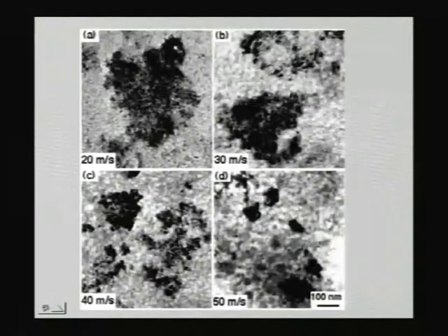And if you use different cooling rates, one can get different grain sizes. As you increase the cooling rate, the grain size of aluminum keeps on decreasing. You get much bigger grains here, you get much finer grains here. So one can achieve finer and finer grains of aluminum at higher cooling rates. And one can also generate the kind of microstructure which I told you before, with aluminum inside that kind of nanoparticle of amorphous.